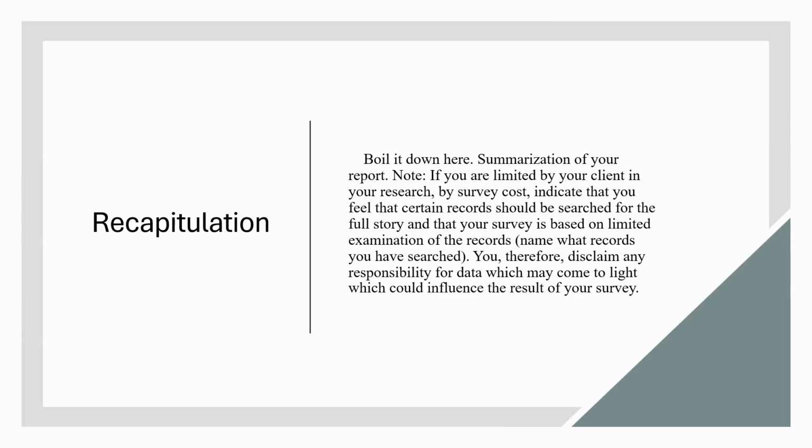Sometimes less is more. If you're doing just a neighborhood survey and they brought in new earth to raise and build on like they do most places these days, but you didn't get to do certain types of soil analysis, or you didn't get to do aerial surveys or watershed surveys or anything like that, if you just did elevation certs and lot and block surveys, that's fine. That's what you were hired for. You don't need to put all of the things that you could have done. It's only the ones that you explicitly feel like needed to have been done. And again, that's something that you'll grow into as you gain more and more experience as a surveyor, how much of that information you need to put here.